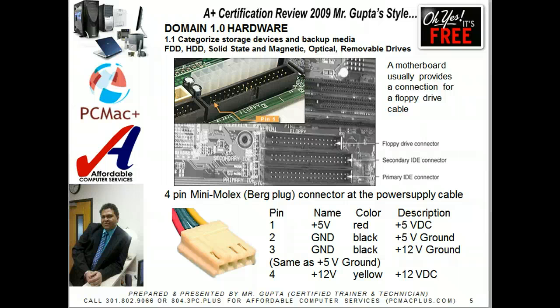This is where the floppy disk drive cable connects to the motherboard. If you look at this controller right here, you see the label on the motherboard says floppy. And this is the pin 1, which tells you right here is the pin 1. This is another picture here. You have a small 34 pin controller for floppy, and then you have IDE controllers for hard drive or CD-ROM. So they are all located together here, where this floppy controller is located next to the P1 connector for the power.